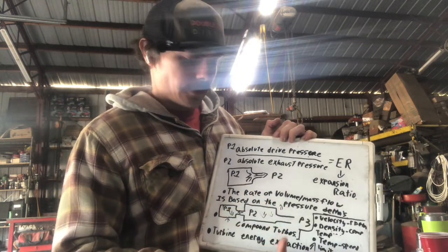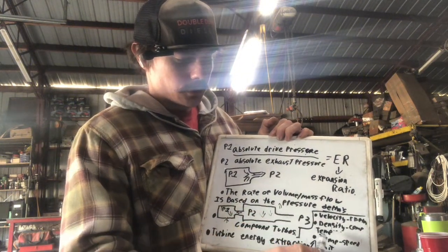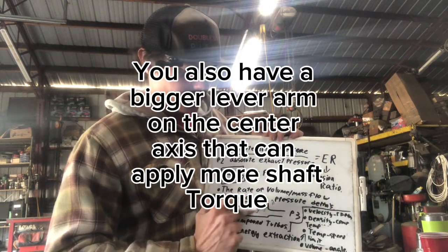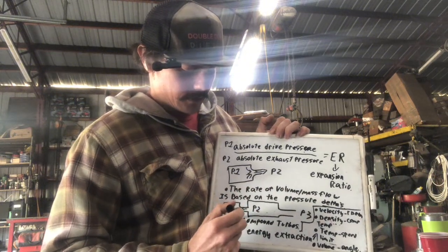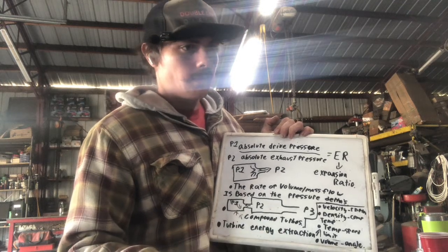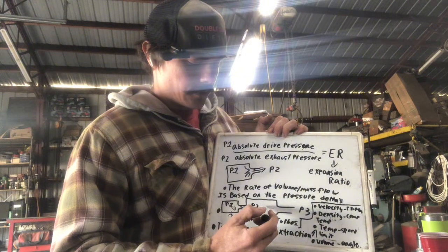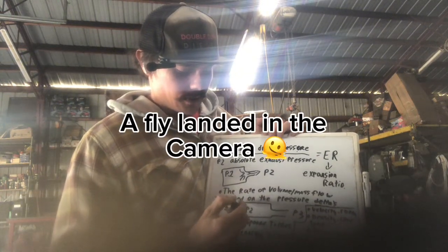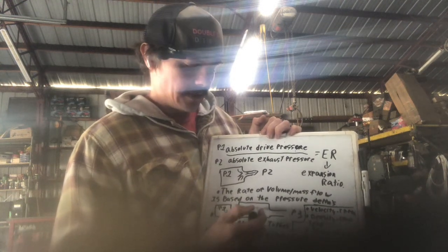Yes, that's correct, because we're trading off pressure energy for mass energy. Now, it does also make the Atmo less responsive, right? There are all the caveats, catch-22s to that. But in this case, we try to size the P1 stage to work correctly and take care of that. And then we can run the atmospheric stage in a state where, when we hit the target pressure that we're looking to run in the inner stage, our interstage drive pressure is as low as it realistically can be.